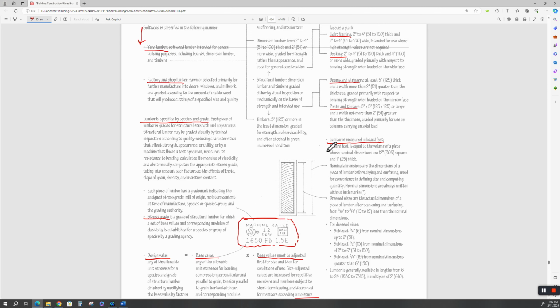Normally you will not be buying lumber for a framing job and ordering so many board feet. You're going to order a bundle of pre-cut studs. And they're not 8 foot long. They're pre-cut if it's stud lumber, and they're graded, and they'll take into account the thickness of the base plate, which is 1.5 inches, and the top plate, which is another 1.5 inches, or the double plate. So they'll be less than 8 feet. Now, if you just go buy a normal 2x4 that's 8 foot long, then if you're going to use it for framing, you're going to have to cut it.